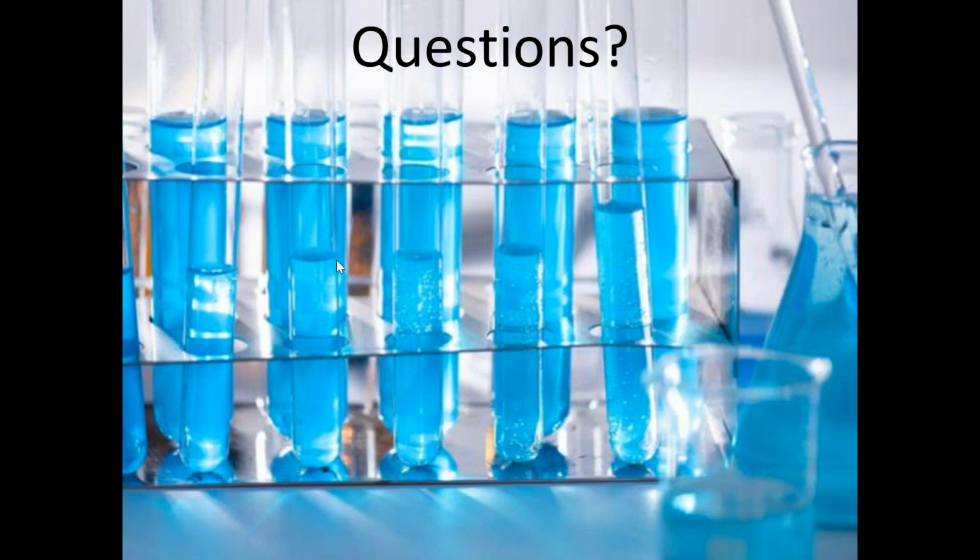We've got a question on the average level and range of alkalinity. In the places I have lived in my life, including Illinois and central Pennsylvania, alkalinity was often between 150 and 300 milligrams per liter. But also in my travels, there are places where it's under 50. There are places out west with high alkalinity that it can be over 400 milligrams per liter. So the range is pretty huge, just depending on where you are.